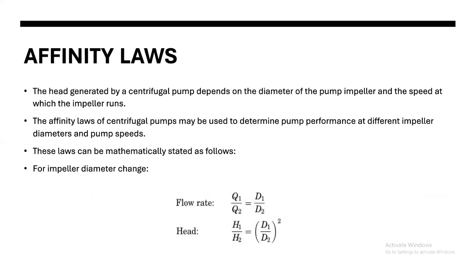Affinity laws. The head generated by a centrifugal pump depends on the diameter of the pump impeller and the speed at which the impeller runs. So the head generated by a centrifugal pump depends mainly on your impeller size and also the speed of rotation of your motor. The affinity laws of centrifugal pumps may be used to determine pump performance at different impeller